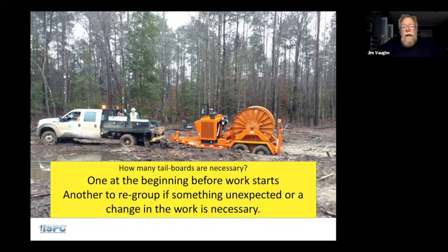But here is one that I have seen a number of times that does not get attention. So this is just another example. This crew's going out to the job site, and they need to position this tugger, and they go out there and get stuck. And the first thing that happens is that everybody starts running around, saying, grab a rope, get the digger derrick over here, put a rope on here, put a line on here, and they're blasting their way trying to get this thing unstuck. And then they end up pulling the bumper off the front of the truck, or pulling the frame skewed sideways, or something breaking. We've even had people break lines and knock the windshield out of a digger derrick truck.